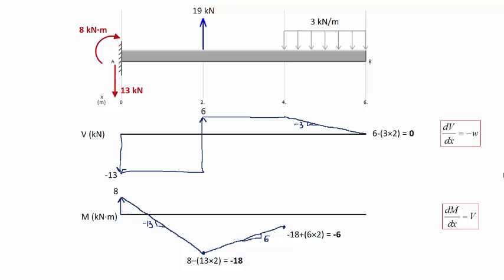And because we have a linear function for the shear force, when we look at the bending moment diagram, through this relationship, we know that the moment would be the integral of the shear force, which means that we would end up with a quadratic function, a parabolic function. And to determine how that parabola is going to look like, remember that the slope of the parabola has to be positive because the shear force is positive, and that slope has to decrease as we go from the right to the left. And this is how it would look like.